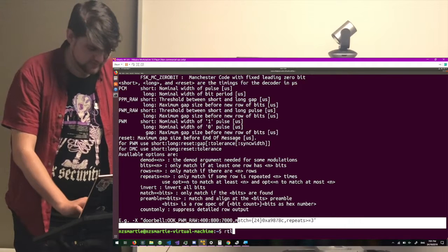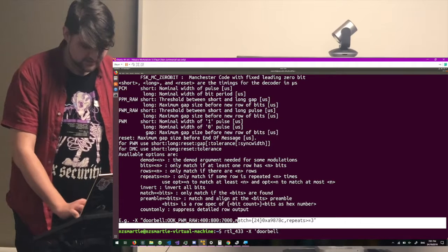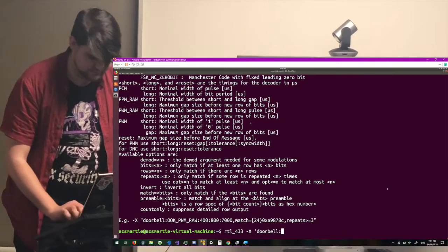So if we go rtl_433 -X, if we go say Doorbell, and we go, what was it? It was Manchester encoding, so let's just scroll up here a bit.